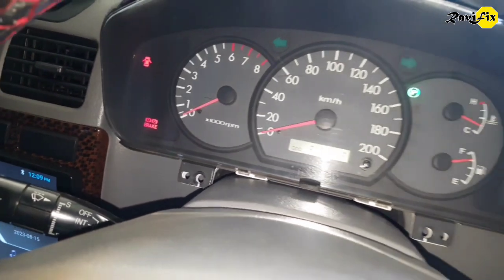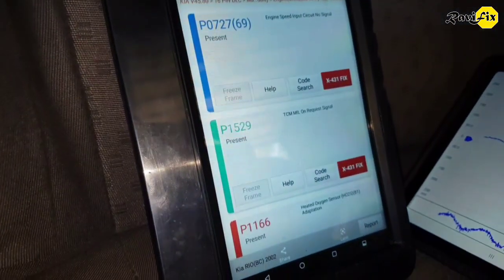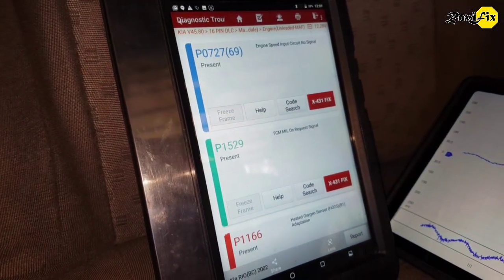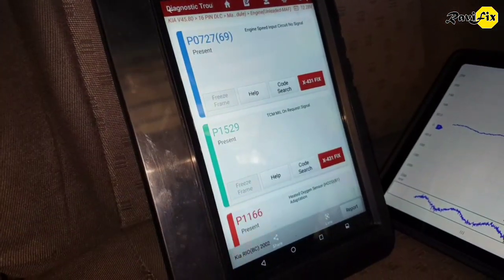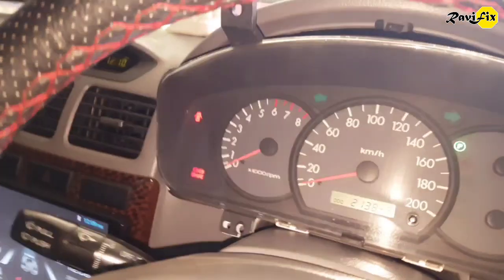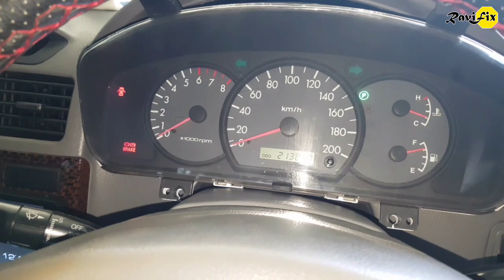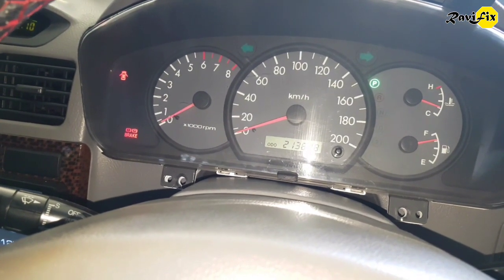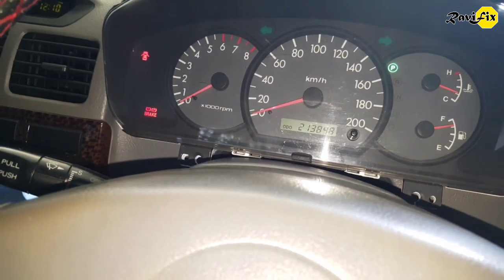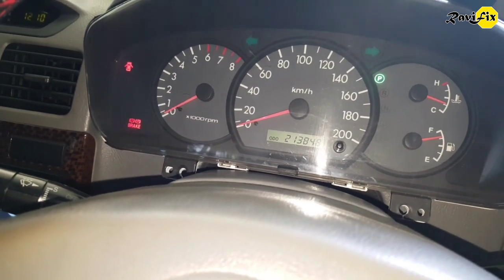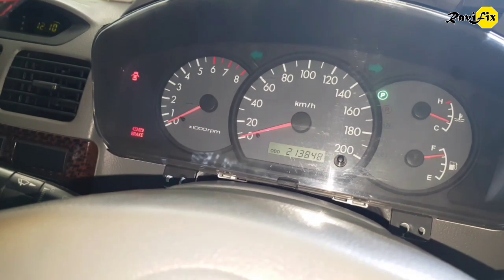Sorry, I forgot to mention that those fault codes are present in the transmission control module, and the transmission control module has already requested the MIL on, but you can see on the instrument panel no check engine light is lit. I believe somebody who worked on this car earlier has bypassed the check engine lamp into another indication lamp, because he was unable to sort out these trouble codes. It seems this tachometer problem and the TCM not getting the RPM signal are parts of the same problem. Okay, let's troubleshoot these faults. Let's analyze the scan data first.